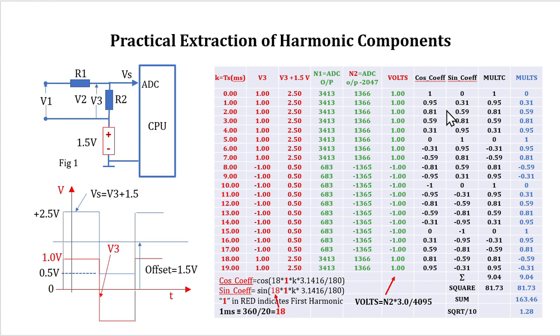Okay, so I hope you have fully understood how to extract the harmonic components, and you also have seen that some kinds of waveforms have only odd harmonics, and there are types of waveforms that do have even harmonics. So in this case, you did not have even harmonics, you only had odd harmonics. In the triangular wave, we had even as well as odd harmonics.